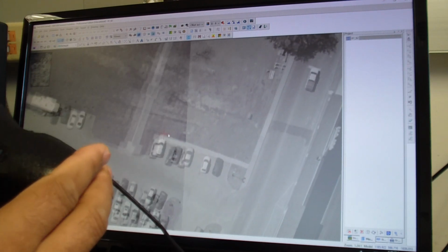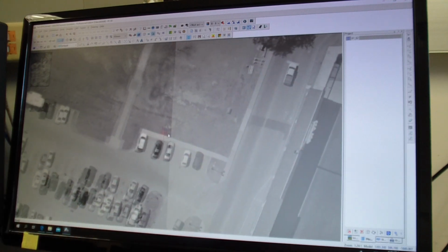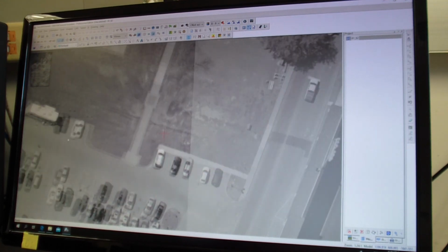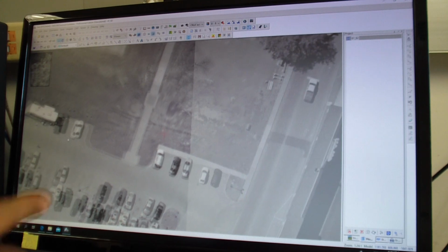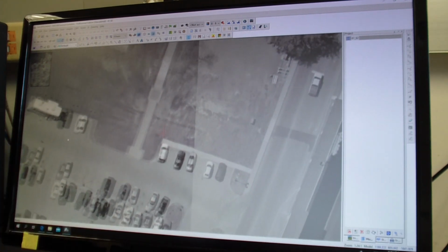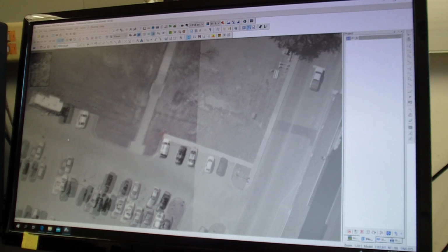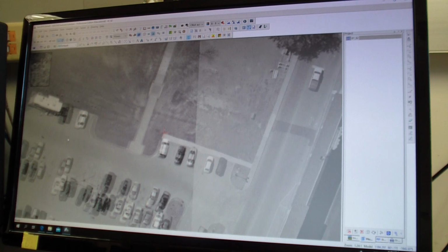Okay, so rotating like that, and we're going to digitize where it is. So if I move it off a bit using the motion mouse, I'm going to digitize, make that red cross here on point number 1. So move it around, make sure it's on that point. When it's on the point, press number 2 on the motion mouse, telling the computer that's where the ground coordinate is located.